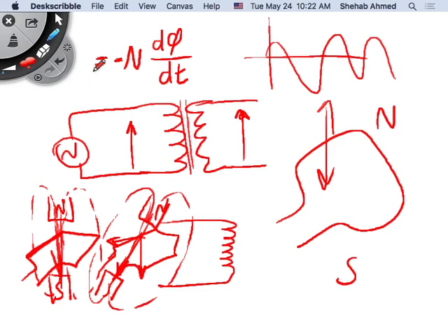This is the most important one for me. Not integration. It is equal to n, the number of coils. Here I have one coil, times d phi divided by dt. It is equal to E, a voltage that will be developed across this turn. Not an electric field, it's a voltage. Fine, a voltage can produce an electric field, a charge produces an electric field, but anyway, E equals n d phi by dt. So there's a voltage developed across the turn because of the time-varying magnetic field.